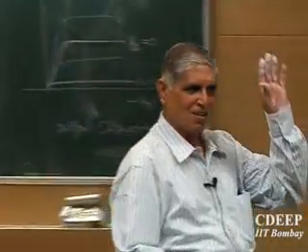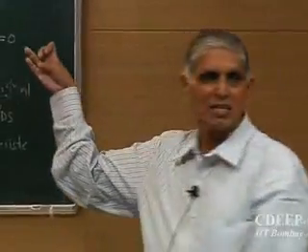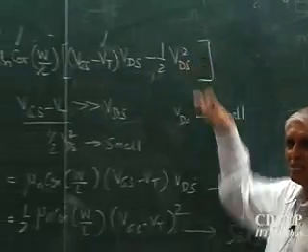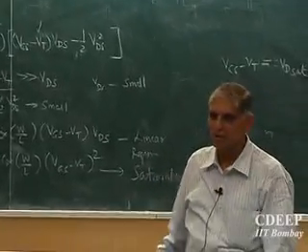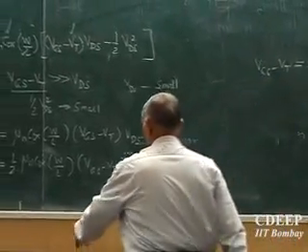Did you get it? Same equation. If VGS minus VT is much smaller, it saturates. That's what we are saying, right? If VDS is smaller, VGS minus VT dominates, and current rises linearly. For anything with VGS less than VT, it is cut off, no current. Is that equation clear? So I must now derive this relationship next time, that is tomorrow. And if I get this, I am representing this by one single equation. Is that correct? By one single equation. So see you tomorrow again.